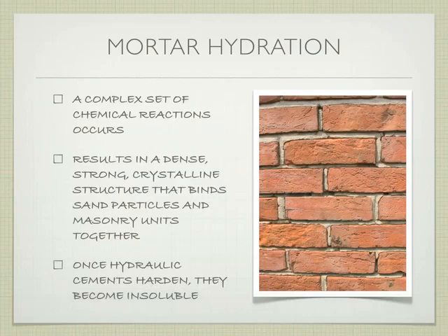So mortar hydration is the complex set of chemical reactions, just like in concrete that we talked about. It results in the dense, strong crystalline structure that bonds all the components together. Once the hydraulic cements harden, they become insoluble. You can't wash them off with water anymore.